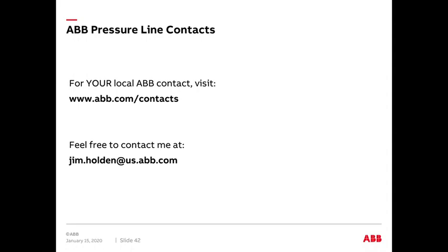All right, next, how is the instrument accuracy affected when remote seals are used or with temperature changes? So when you're using a remote seal, that's the good thing about the ABB, is when you have an all welded construction through that capillary tube, which can be only a few inches, or it could be several feet long, but with the all welded seal, and you completely have a filled capillary tube tested with no leaks, you have very, very minimal, if any, effect on your accuracy by doing that. We'd have to pull up a data sheet and go through some of that, but it can be very, very minimal effect with that. So what was the second half of the question, Wayne? Temperature changes, temperature is affecting it.